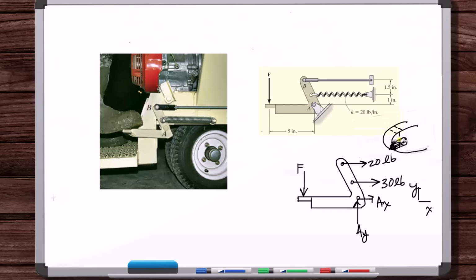Well, when we talked about coplanar distributed loads, to model a distributed load as coplanar, the requirement was that, so let's put this same parabolic distribution at this end, at each point on the distributed load curve, the pressure doesn't vary along the thickness. It's constant. That's the requirement. And if that's the case, then this is symmetrical with respect to the center plane of the link, right? This load distribution is symmetrical.